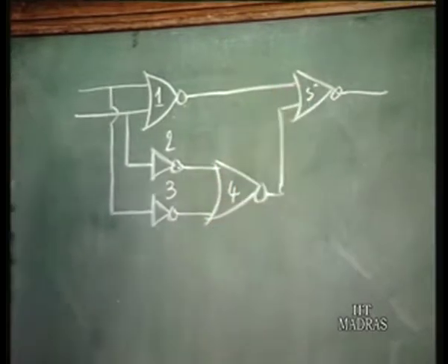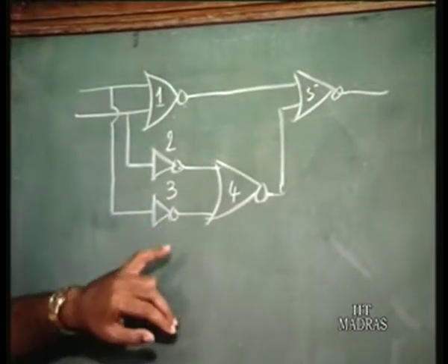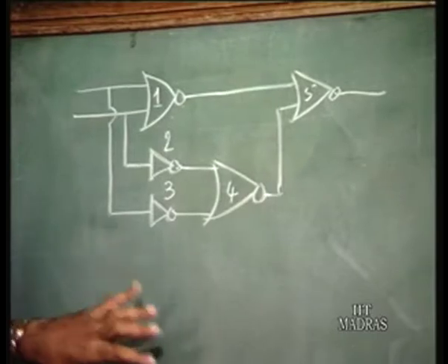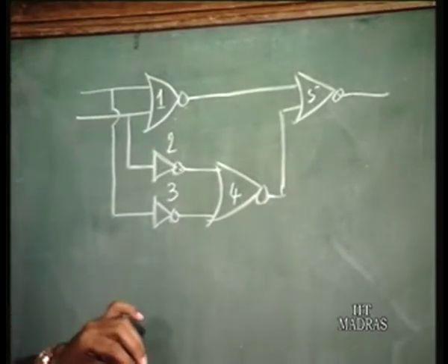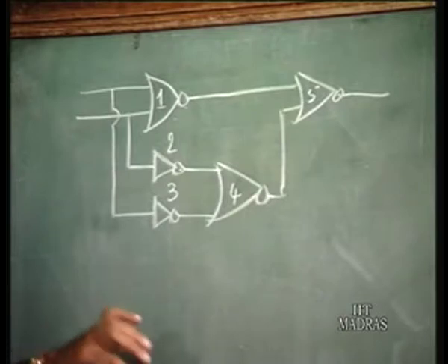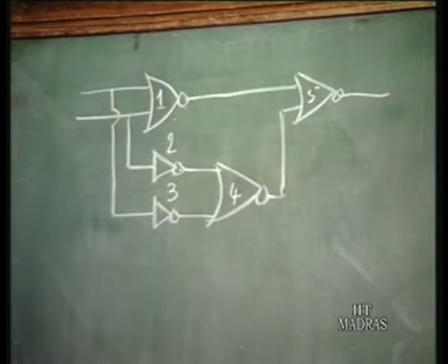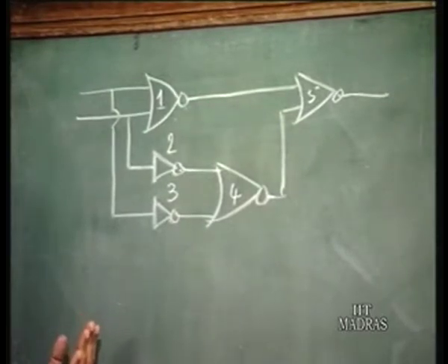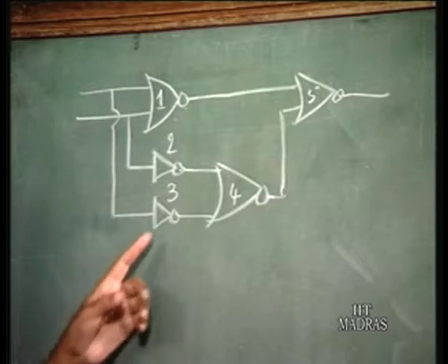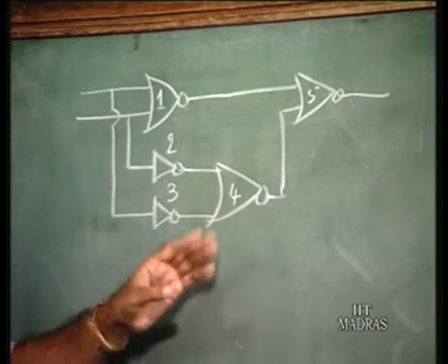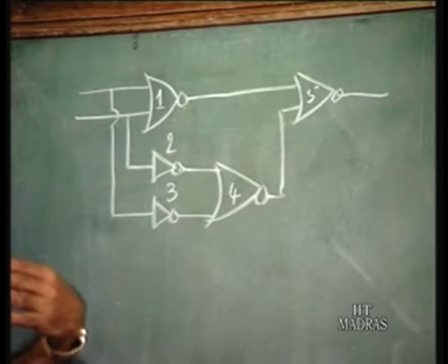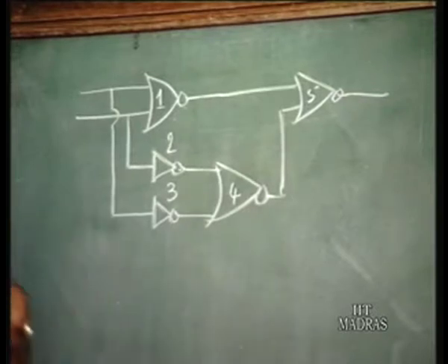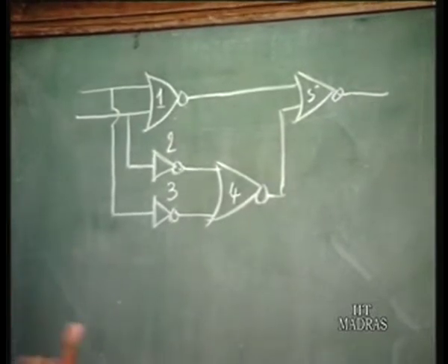Each gate output is represented by a node at the transistor level, and the number of collectors connected to the node represents the number of inputs to that NOR gate. And the number of fan outs of that particular gate is reflected in the number of collectors of the subsequent transistor, or the next transistor.